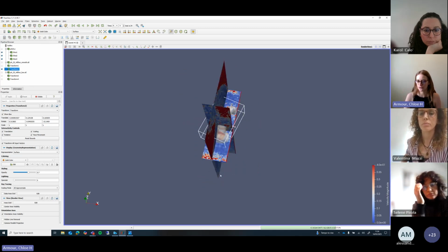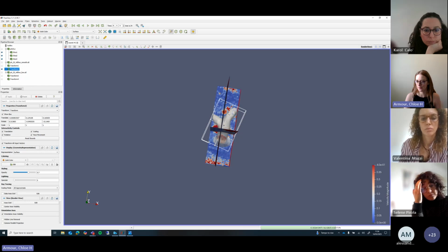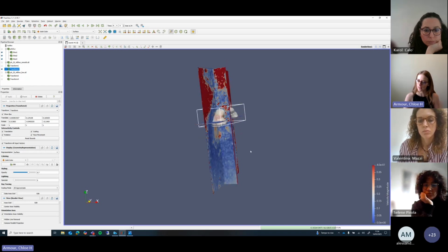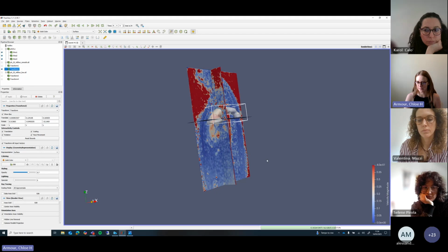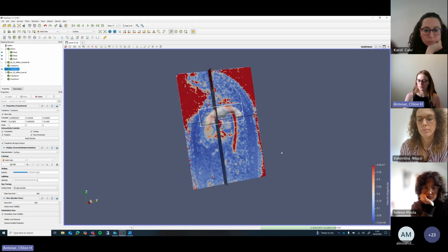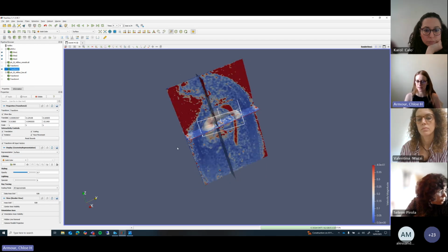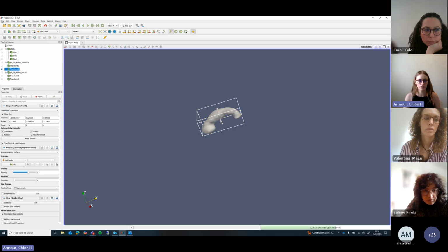Here in the pulmonary artery, I'm looking specifically for that bifurcation point. It does become a bit trial and error, a bit manual, but that's especially important where Selene mentioned that once we do the CFD simulation, we're reverting back and iterating, checking how well matched the results are and if we need to make any modification. So once we're happy with the alignment, we can take this geometry and simply save it from ParaView with file, save data, as an STL.